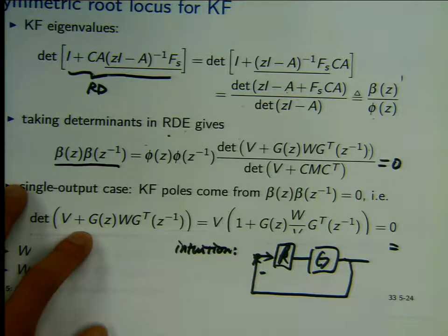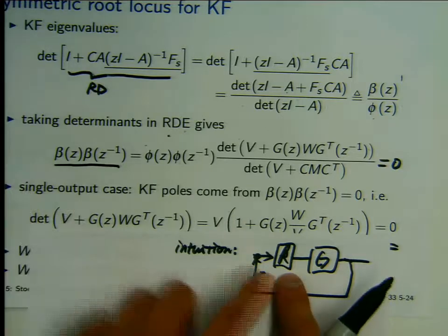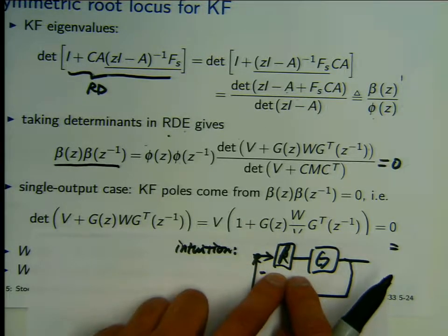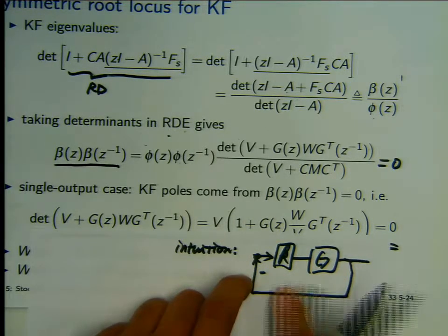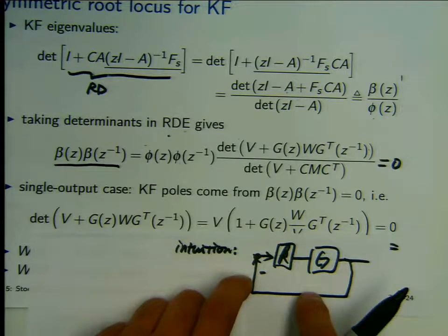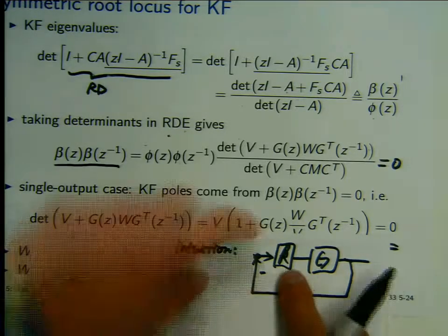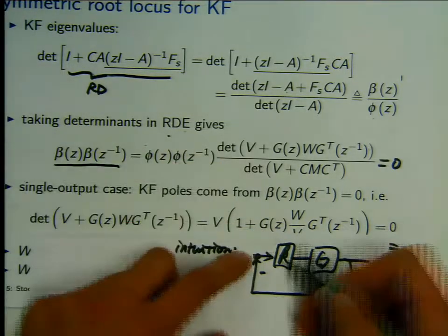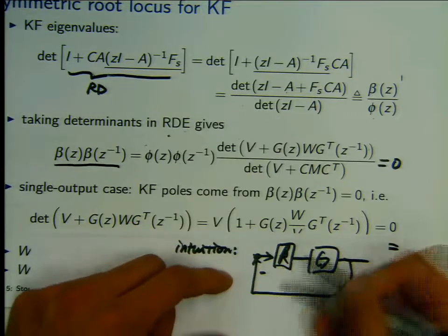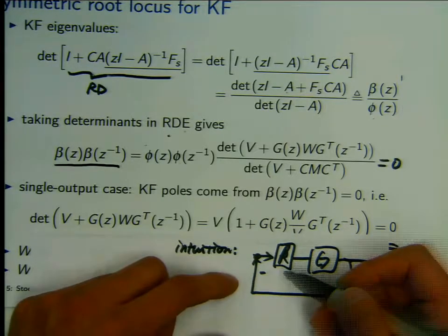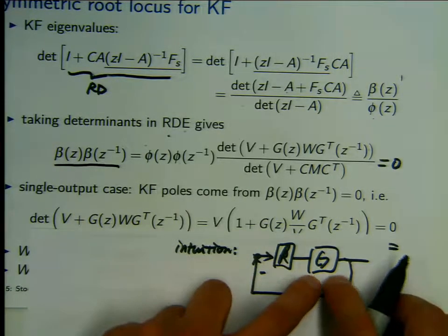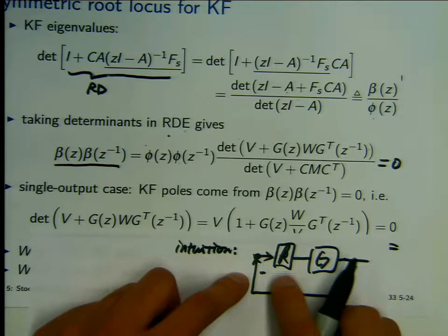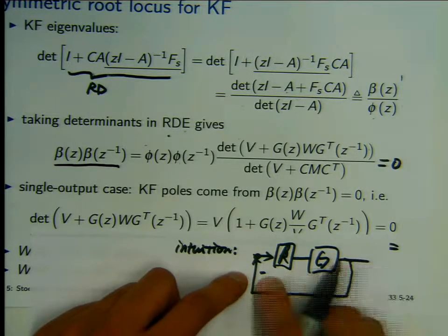This is the root locus analysis. It's a review. Let's do the first case. If K approaches 0, what are the closed loop poles? No, there's still poles: the open loop poles, right? If this is approximately 0, then essentially I don't have the feedback. I cut off the feedback connection. Then the poles are the open loop poles. Then if K is going to infinity, then the poles are the open loop zeros.